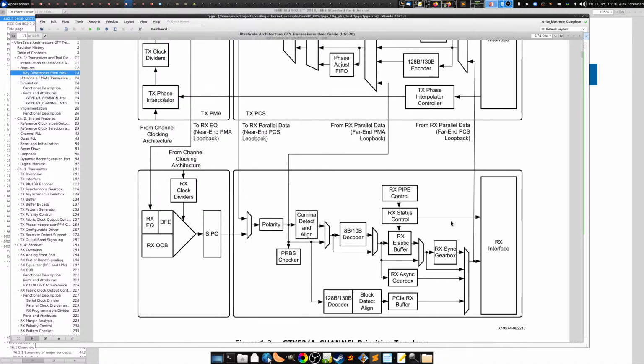Anyway, the focus of today is going to be what's going on in the analog front end here. Because what we're getting out of this thing are these strange bit patterns. So where are they coming from? They're not going to be coming from the NIC at the other end, because that's going to be sending valid 10 gig data. So they're not going to be coming from the link itself. They're going to have to be introduced by something inside the receiver. There's nothing in here that can really generate bit patterns. It just gets passed through. So that leaves us with basically the analog front end, and something in here is not working correctly.